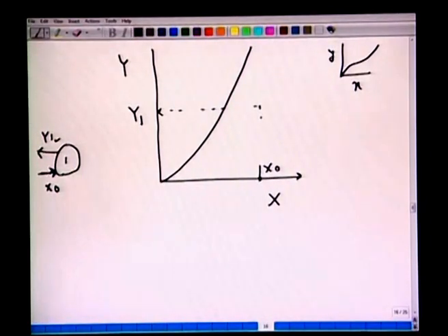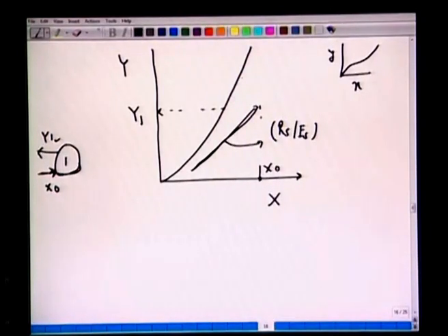Okay. So, we mark here y1, x1, and if you look at the operating curves, now it's a linear and positive slope. So, we have a linear curve with the slope of plus Rs over Es. Okay. And if some equilibrium curve is like this, it's possible that this operating curve may extend to hit this, and we will call this a pinch. It's a pinch point, right.